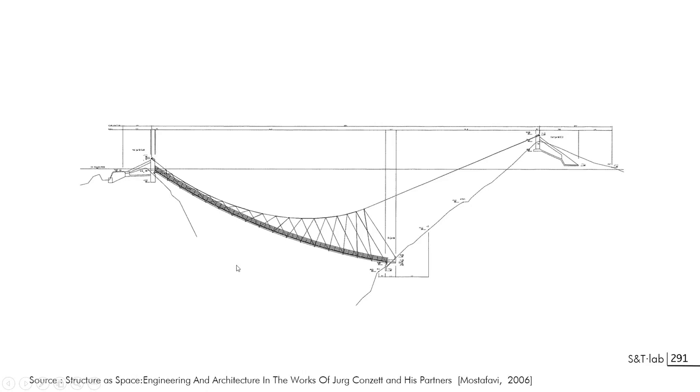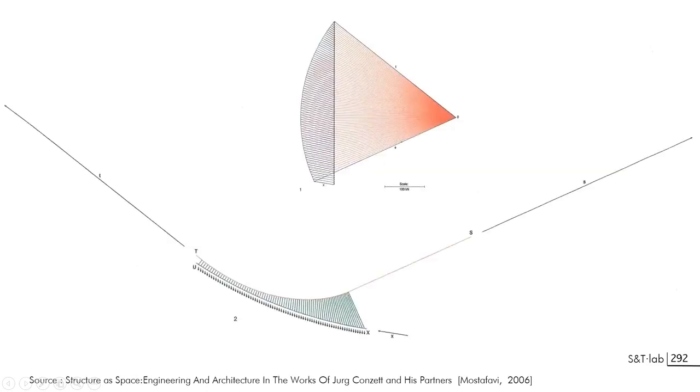You can find the first design of the geometry of this funicular hanging bridge, a funicular here, and you recognize the rays of the funicular polygon. At the end, you will see that you have a series of loads that will be applied here that will be equilibrated by 2 segments of the lower truss line and by the hanging arch here.